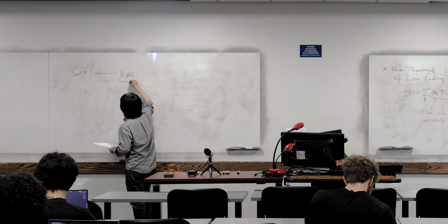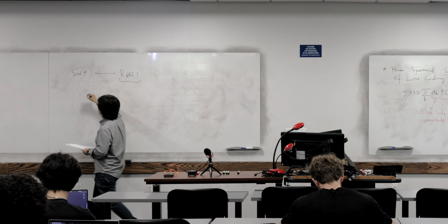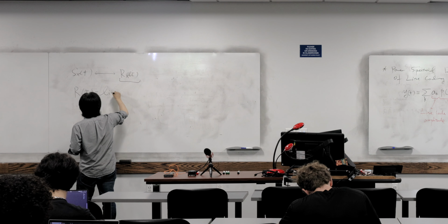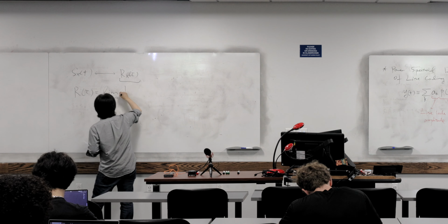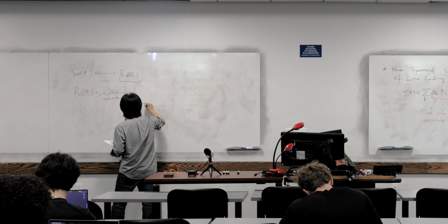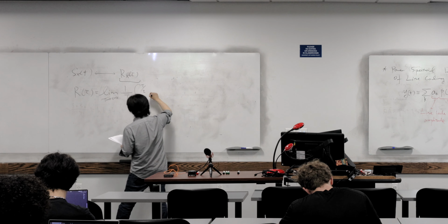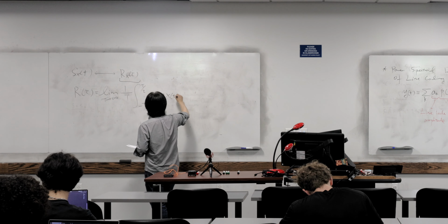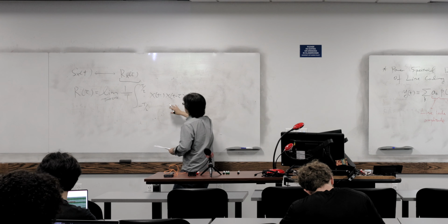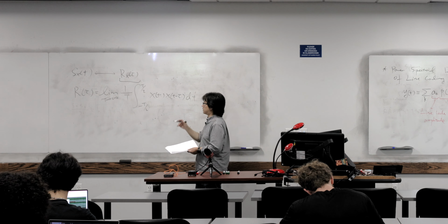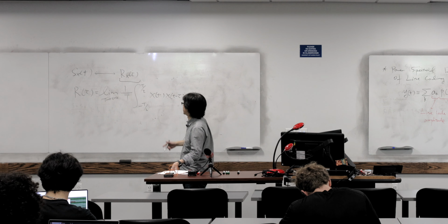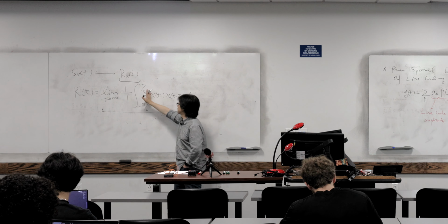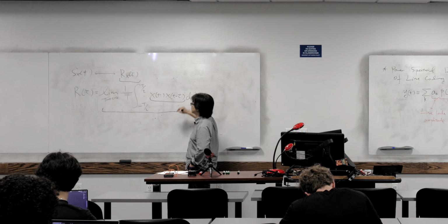Then now the goal is to compute this guy. How can we compute that? Using the definition here. This equals, as T goes to infinity, 1 over T times the integral of this guy, and inside is x(t) multiplied by a shifted, delayed version of itself, which gives R_x(tau). Is that hard to compute? Ignore this part. The key is to compute this guy.